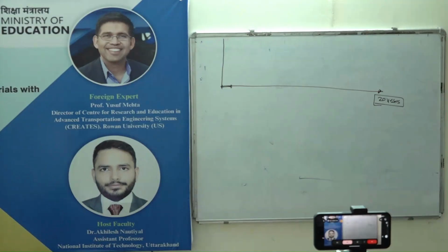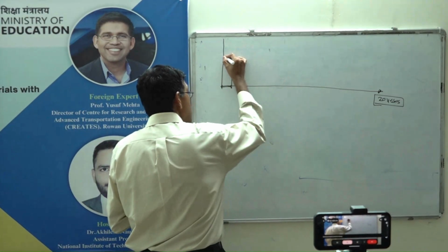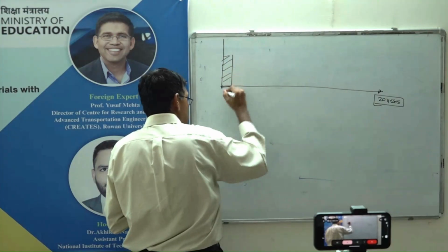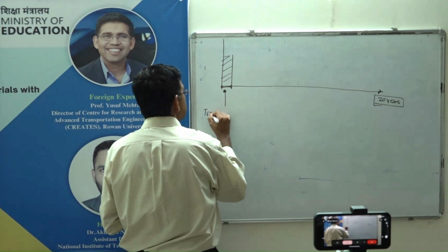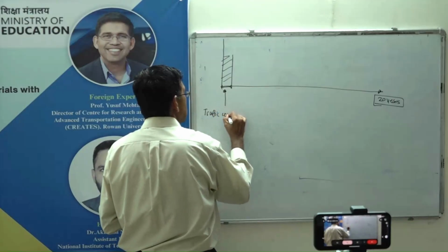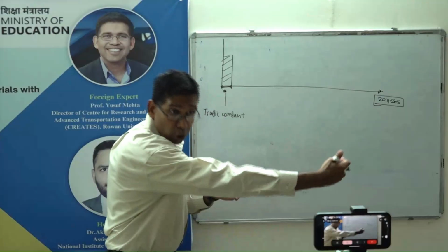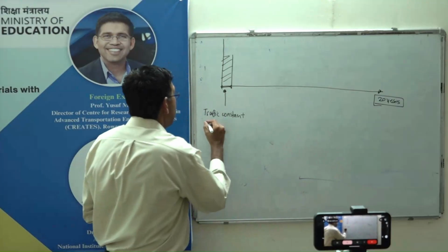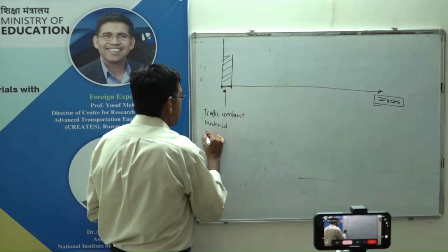So, having said that, in that 15-day period, in this block right here, you are going to assume the traffic is constant, does not change. That means my daily traffic is consistent over the 15 days, right? Material property is constant and environment is constant.